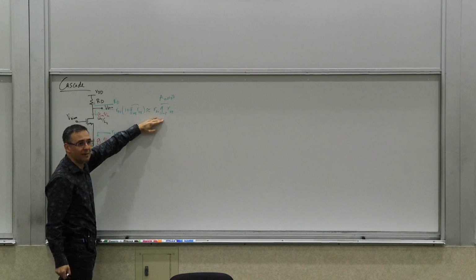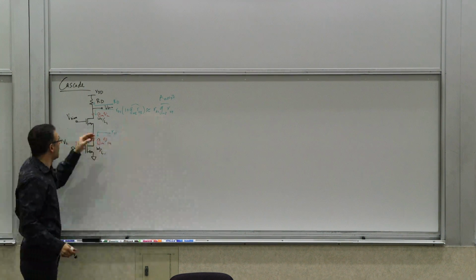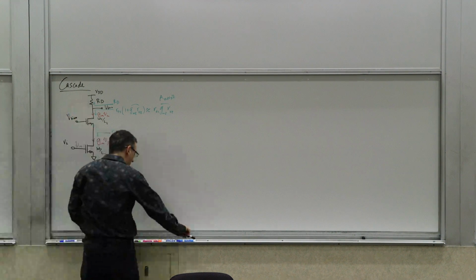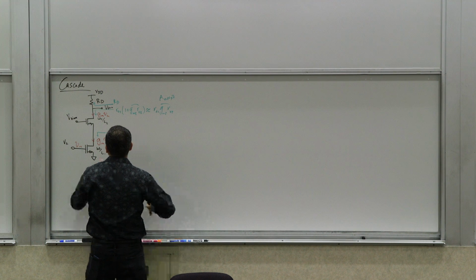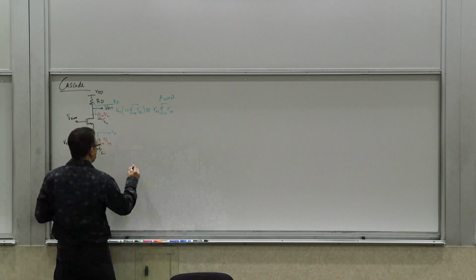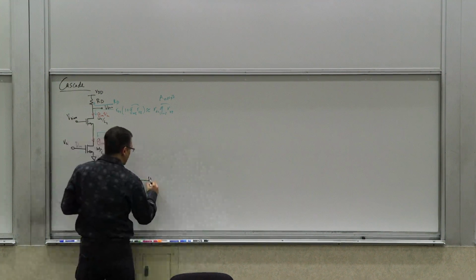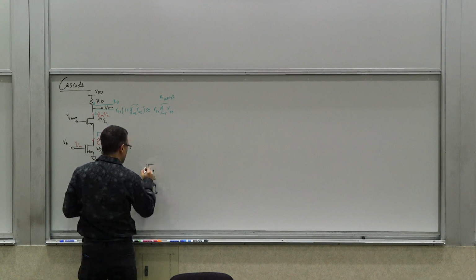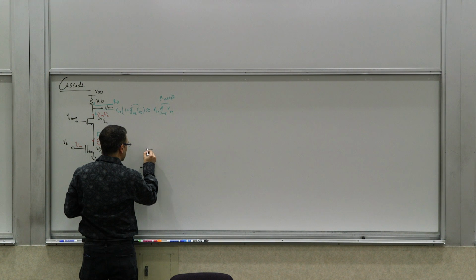So obviously, we have to make that large. The way to make it large was to put another Cascode here as the load, which represents a similar kind of load. So if you wanted to really maximize the gain, we went to something that looked like this. And we did this last time. I'm just reviewing this for you quickly.